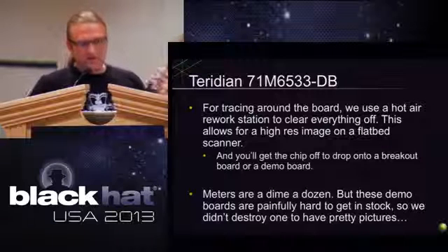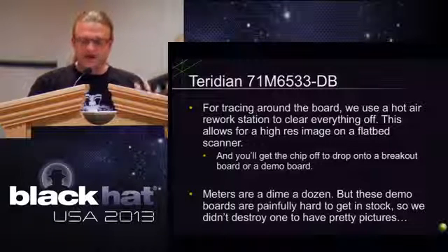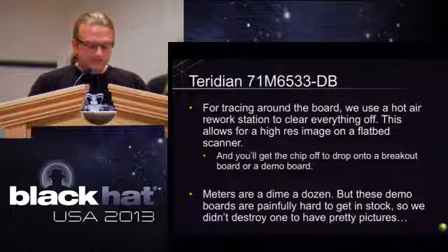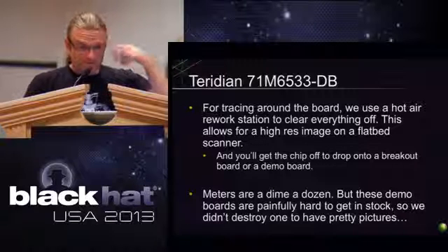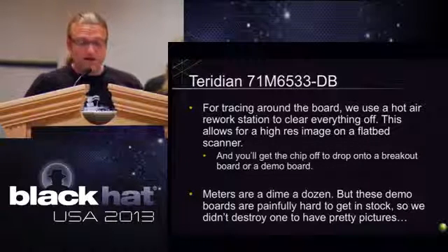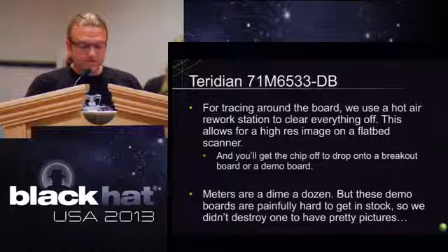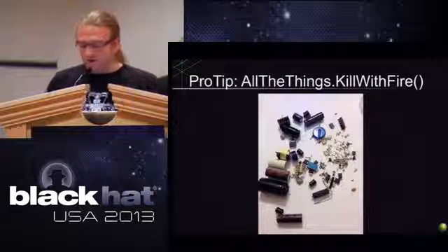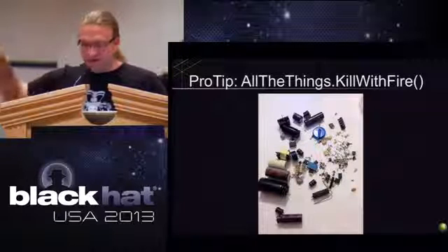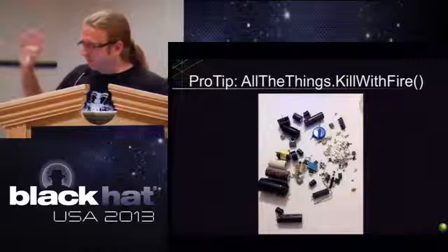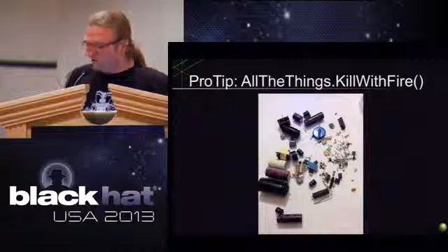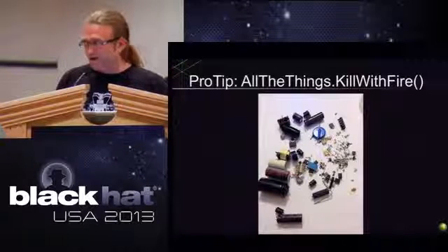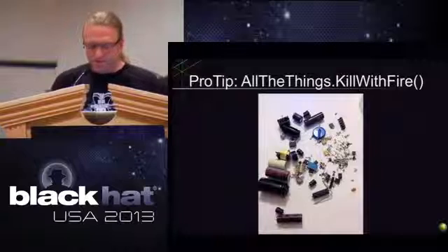Second thing, when you start wanting to look at these types of devices and how they work, you really want to figure out what the PCB is doing around the SoC just as much as you want the SoC. One of the tricks that we have started to do more and more is I take a production board and I desolder everything. That's all the detritus that was on the board. I'm sure it's important for it to run, but I don't care at this point. I take that, I throw it away.